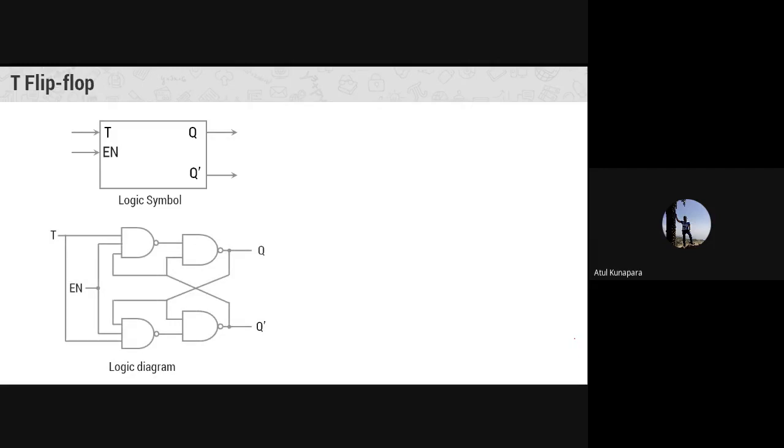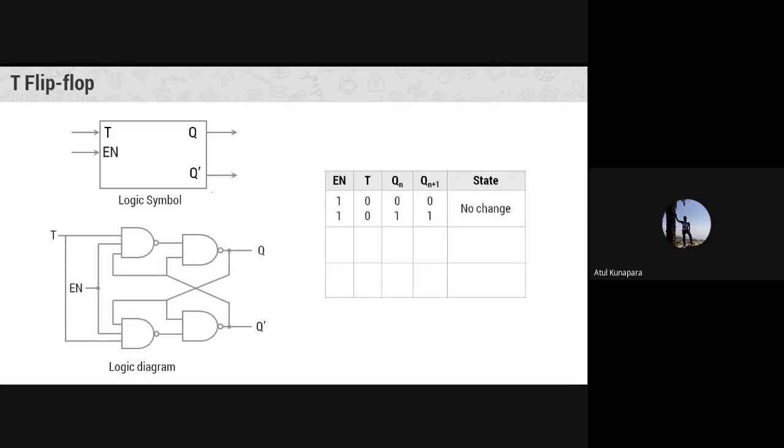It is very same as what we have seen in the previous case. But here the only thing we have done is we have combined the 2 input terminals J and K together to give a single input T. That is what we call a toggle input. So this will work like a JK flip-flop only. But here, as we have combined the 2 inputs, we are only providing one input. The cases will be reduced.